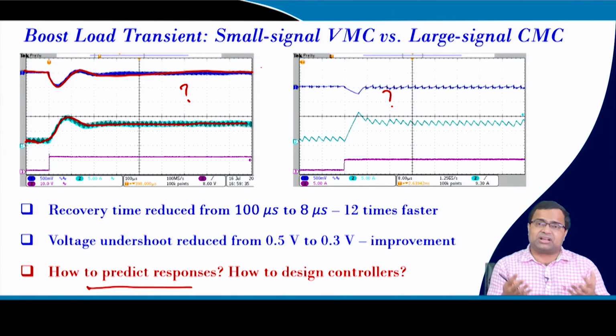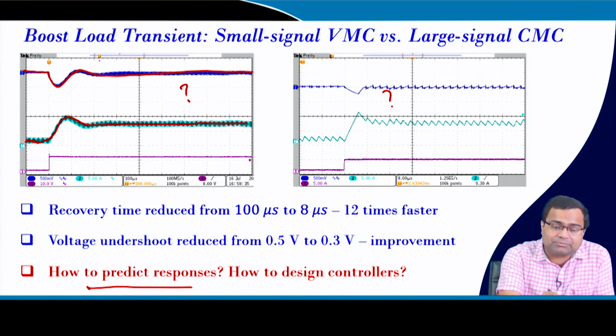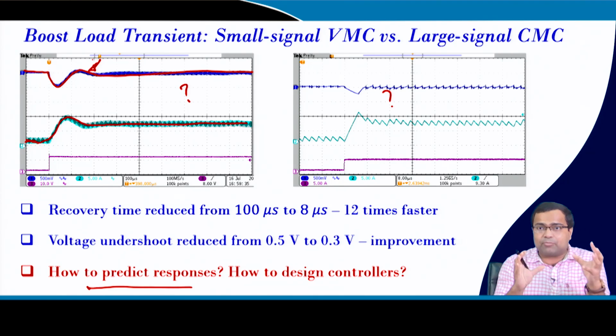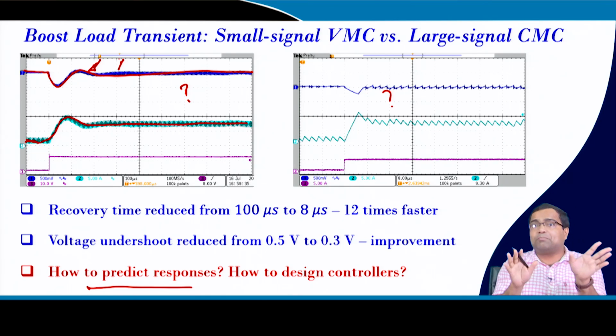Then we get the AC transient response using that linear model, add the operating condition, and compare with the actual switching simulation, and you will see something similar. The red line is the result obtained from the linear model, and the actual switching converter is the blue trace, which we will compare in the subsequent lecture.